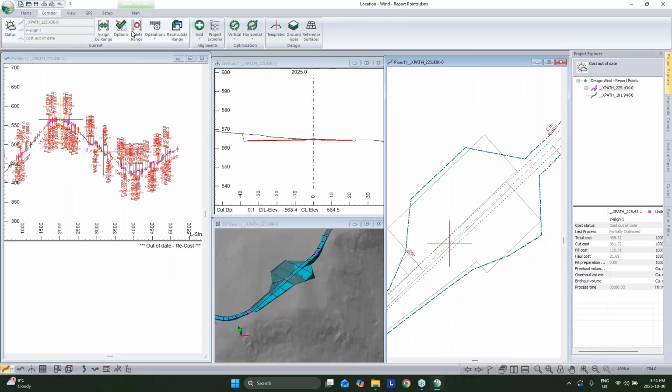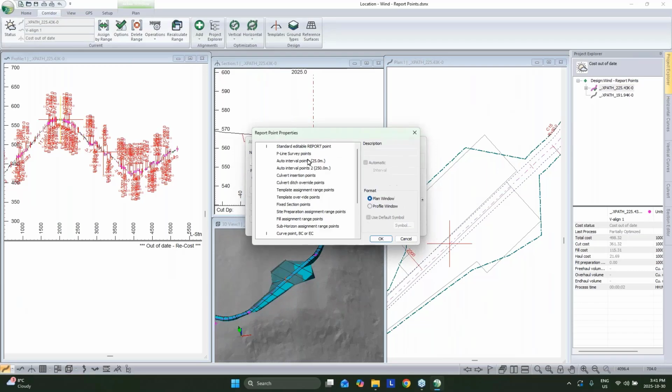We could go in here and crank this down and say, well, 25 isn't capturing that, maybe we want to go smaller. But if we go too small, and we're doing it at this level, it's going to be a global setting. So we wouldn't want to put this in at 1 meter because, in terms of performance, that's effectively making our road 25 times longer in terms of computation time.